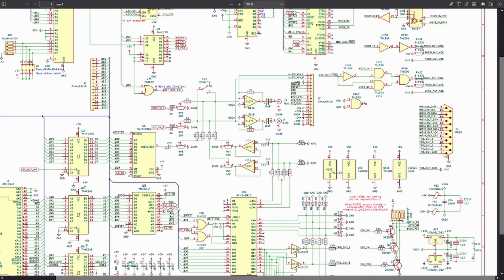outputs. And then I decided to build a stereo amplifier or mixer circuit right here using standard op amps, TL074s, and mix the signals together. The mono signal from the SN76489 is mixed onto left and right equally. The YM2612 is directly mixed onto left and right, and the AY-3-8910 mixes channel A to the left channel, channel C to the right channel, and channel B to both channels. And therefore, I can generate a stereo signal.